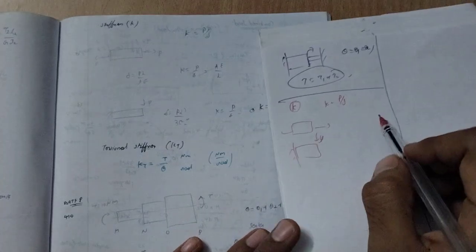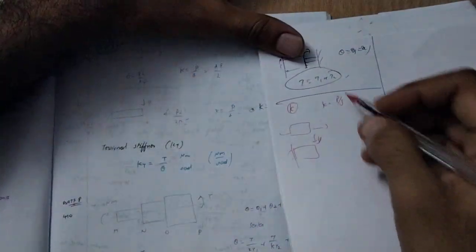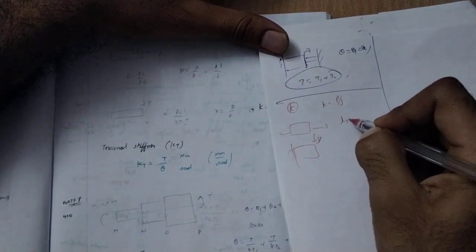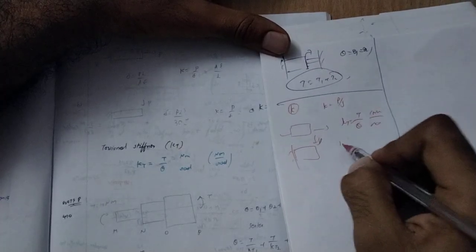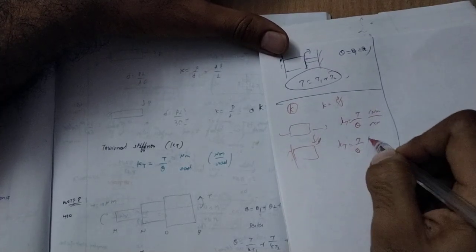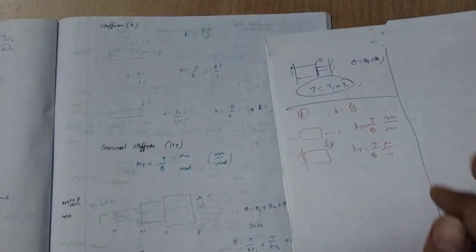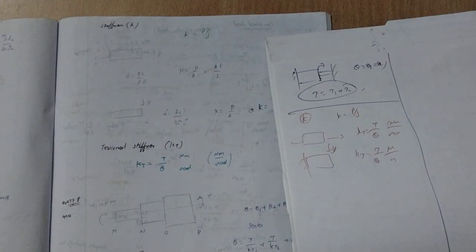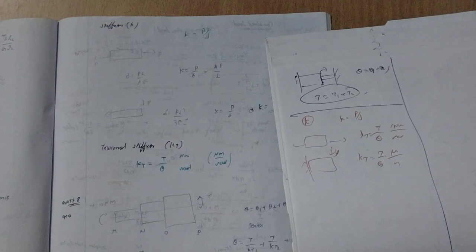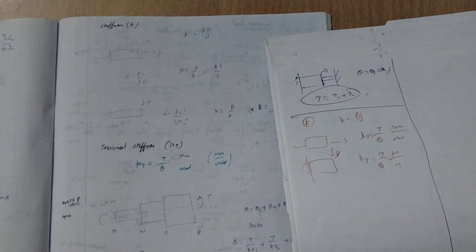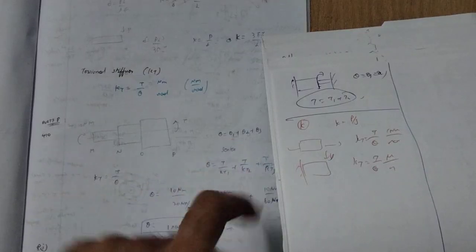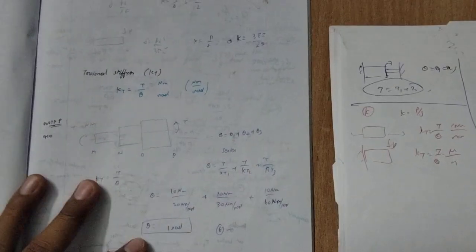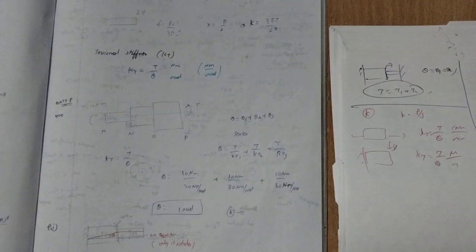Okay, so based upon this we can calculate each, and in the same way for torsion, KT equals torque divided by θ. Okay, this is Newton meter per radian. Okay, KT equals torque by θ, Newton meter per radian. Okay, this one is in series, θ equals θ1 plus θ2 plus θ3. Okay, each and everything will rotate.